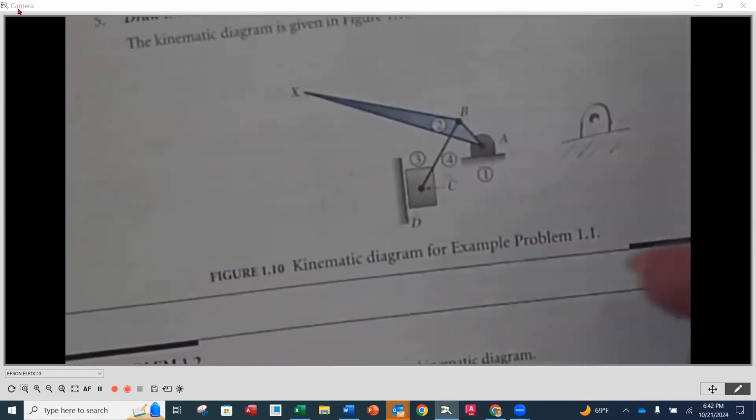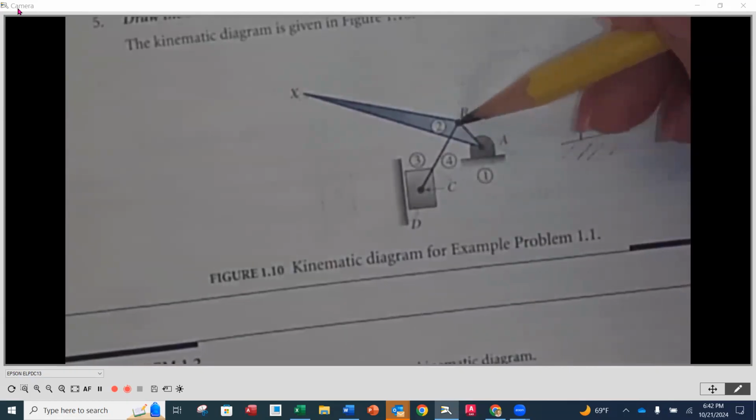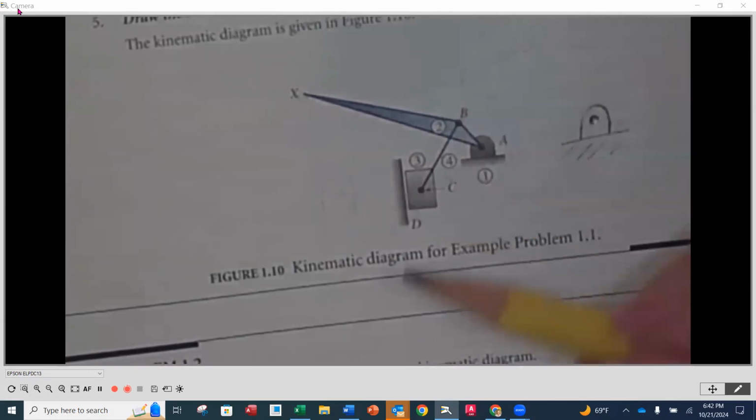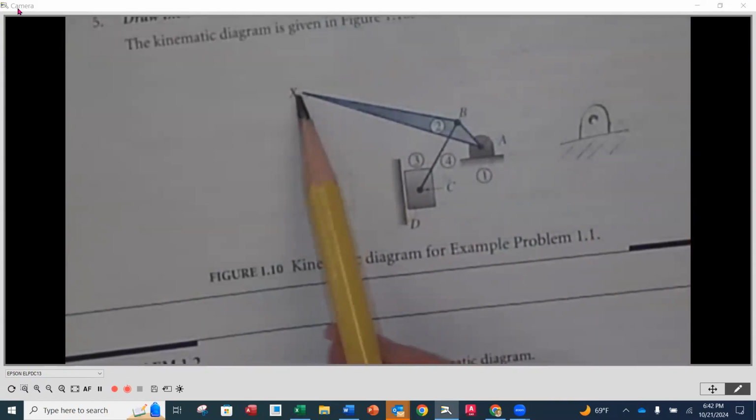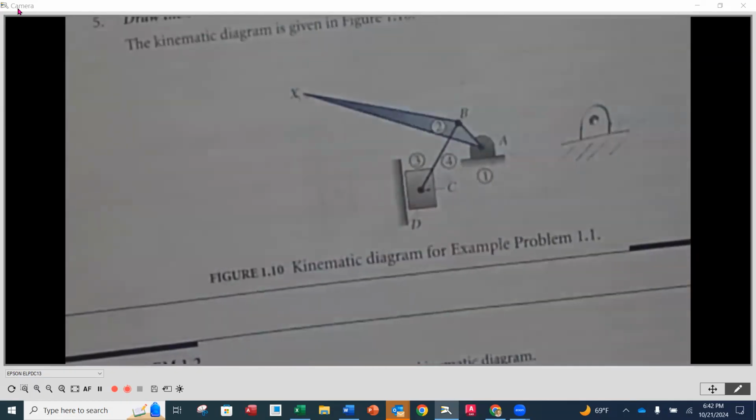This would be like a hatched portion. So over on the right, I kind of sketched that out, okay? When we look at a simple link, it is simply going to be a line connecting where the joints connect. So this would be, if we weren't interested in that point of interest X at the end of the handle, this handle could just have the distance between A and B here, okay?